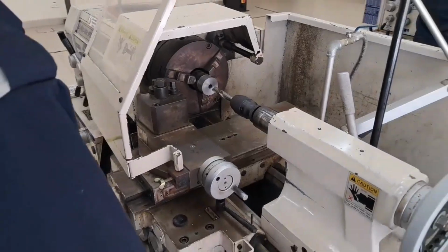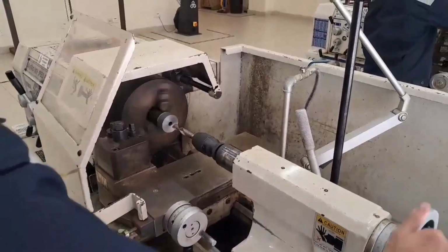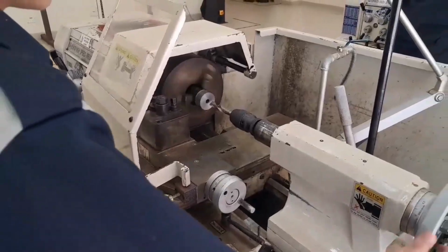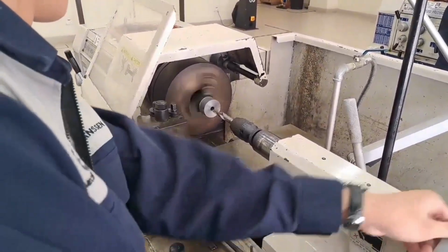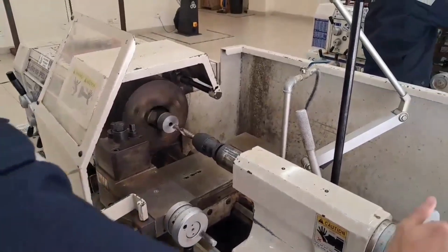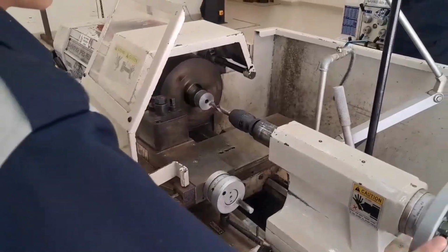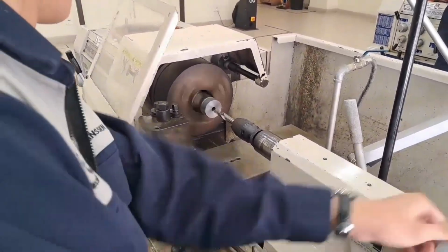There are several improvements that can be implemented. First, a preventive maintenance schedule should be carried out regularly to inspect the pump, clean the components, and replace worn-out parts before failure occurs. Second, installing pressure and flow sensors can help monitor the pump performance in real time and detect any abnormalities at an early stage. Third, improving the part alignment and using high-quality sealing materials can reduce leakage and energy losses. Lastly, proper training for operators is important to ensure that the pump is operated correctly and safely, reducing the risk